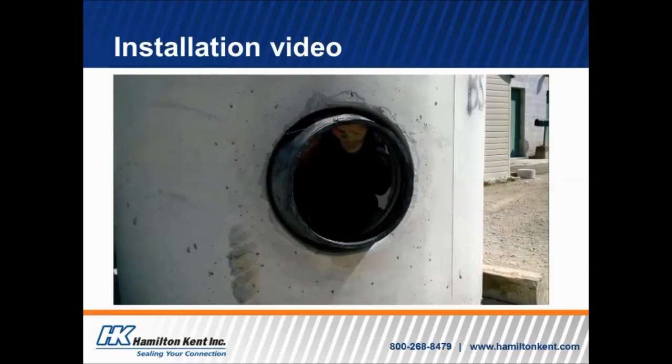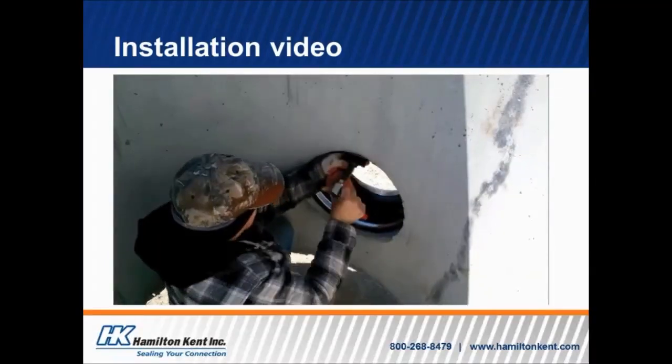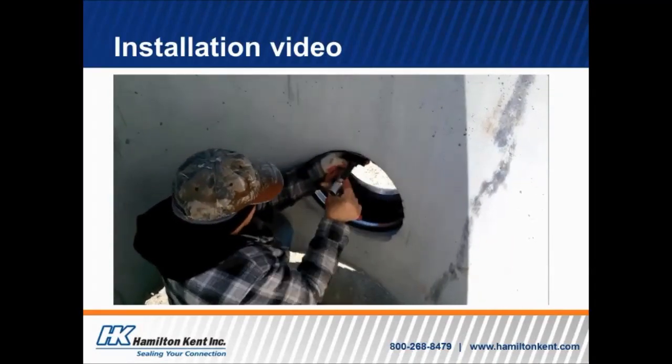So now he chose to go inside to do it, but again, you could do it from the outside and reaching through, and then just showing him tightening it down some more from the inside. So again, you can see he's using a ratchet style, and as he's tightening up, it just tightens that hoop on the inside of that boot.